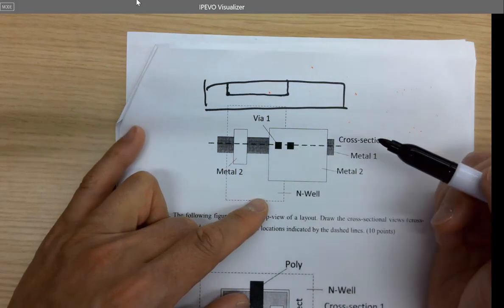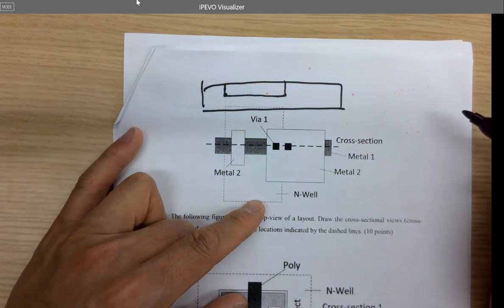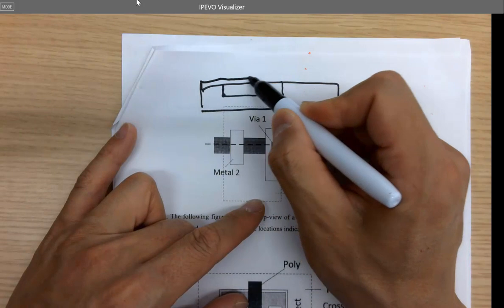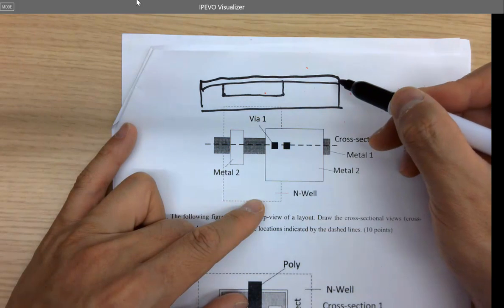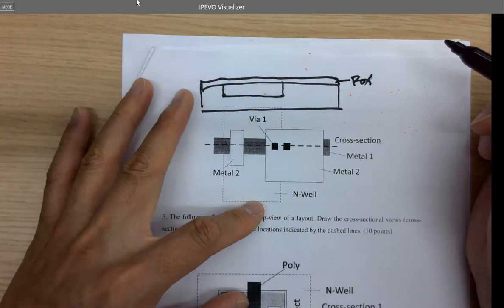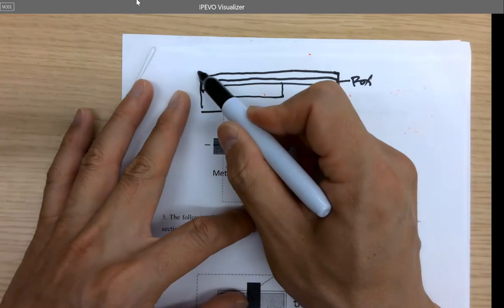So since you have an N well, do you have a fox on the top or not? Do you have an n-select or p-select? You don't have the select layer, let's assume you still have the fox on the top. They probably can dope that N well first and then deposit another insulation layer on the top, right? Do you have poly? No. You have metal 1?